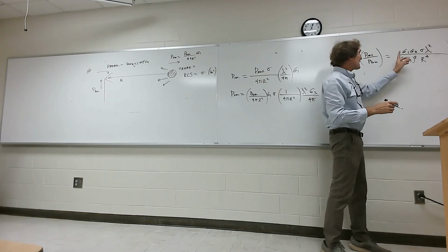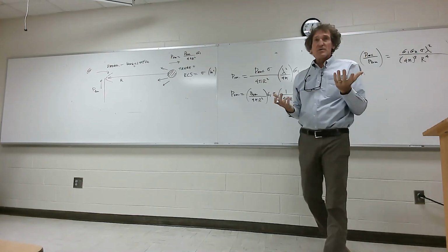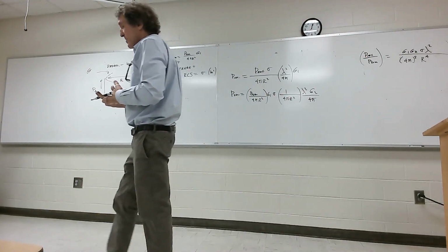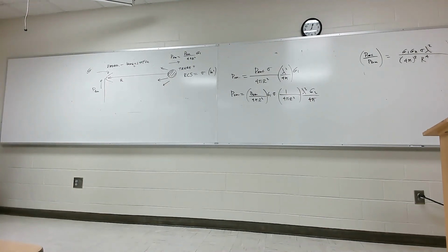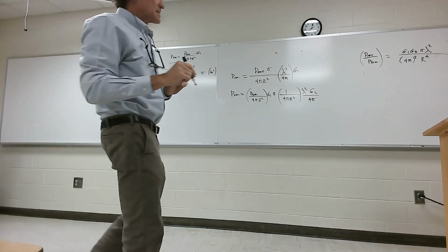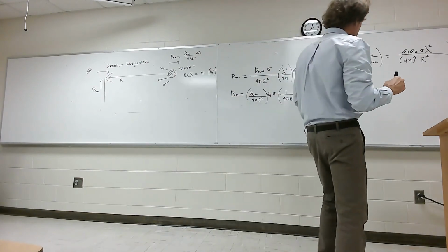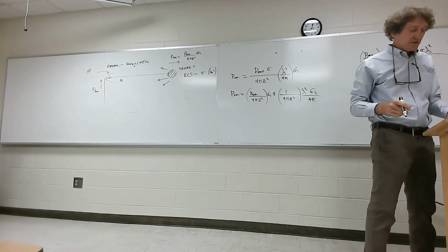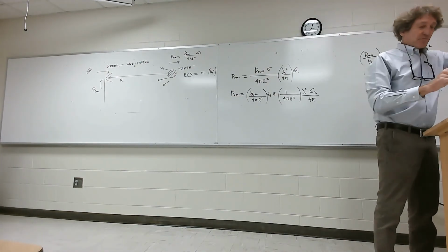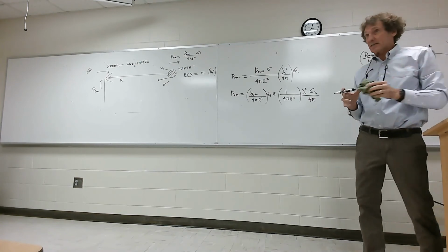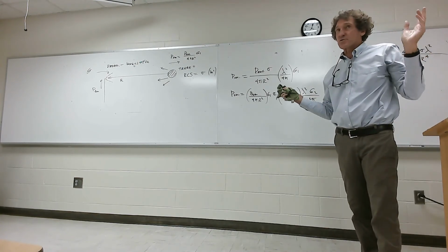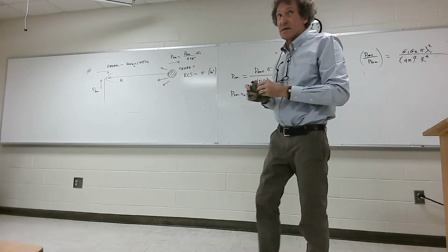He may use directivities instead of gains, but usually, if it's a monostatic radar, the gain of the antenna is the same because they're using the same antenna. Gain 1 is gain 2. If they have 2 separate antennas, then it would be different. But generally speaking, they're the same. And that really is called the radar range equation. That's the first thing you have to know about radar. Does that make sense to everybody? And these are just straightforward plug and chug kind of things.